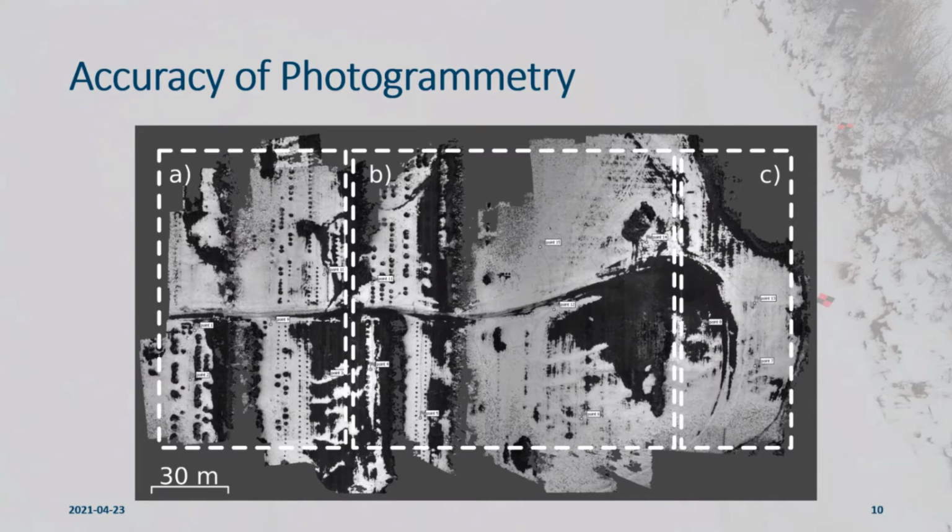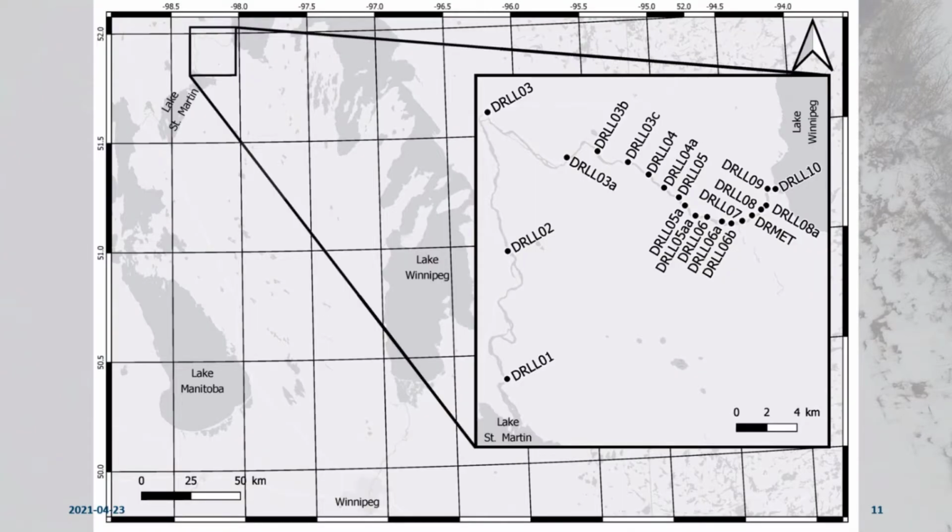And we got pretty good results with about a maximum of 3 centimeter vertical error, which for us is certainly fine. That's around the resolution we would hope for from something like a field GPS unit. So we answered our question there. We didn't have any significant incurred error.